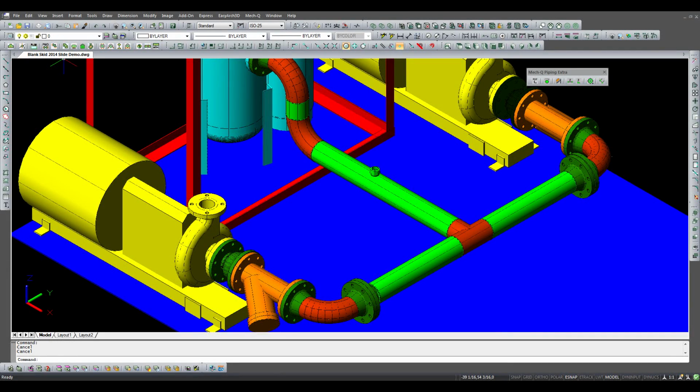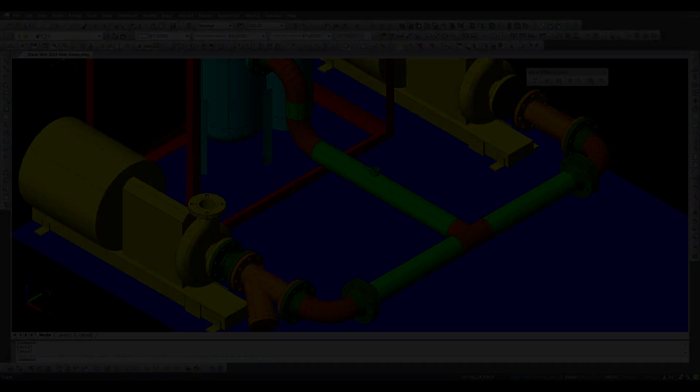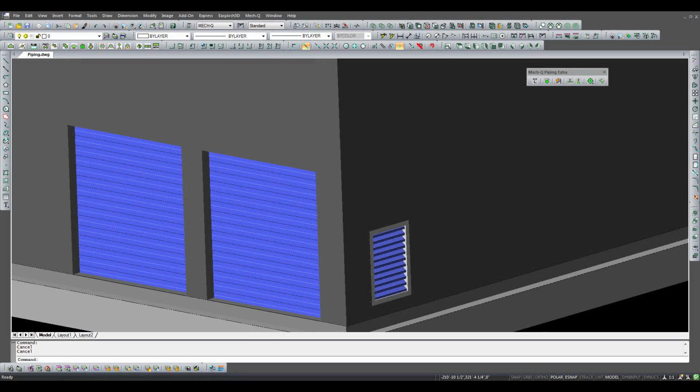To complete the manifold, all we need to do is install the pipe and the weldolet, and the manifold is ready for tagging and dimensioning. All this was done without drawing center lines or making calculations of any kind. The slide command only requires 4 point picks to slide an object into position regardless of the object's orientation in 3D space. In this next example, we'll look at the chiller manifolds in our central plant project.